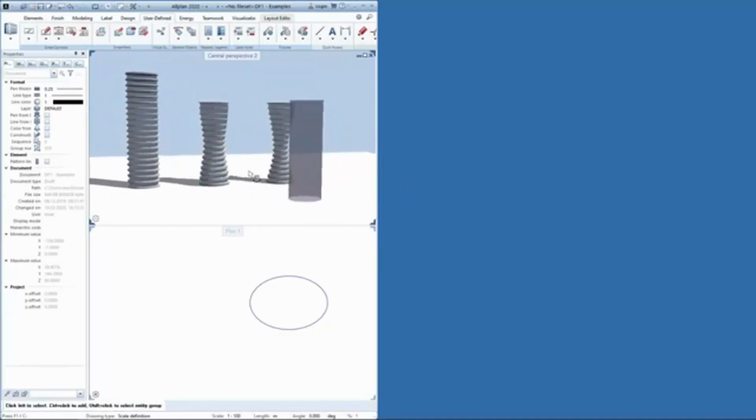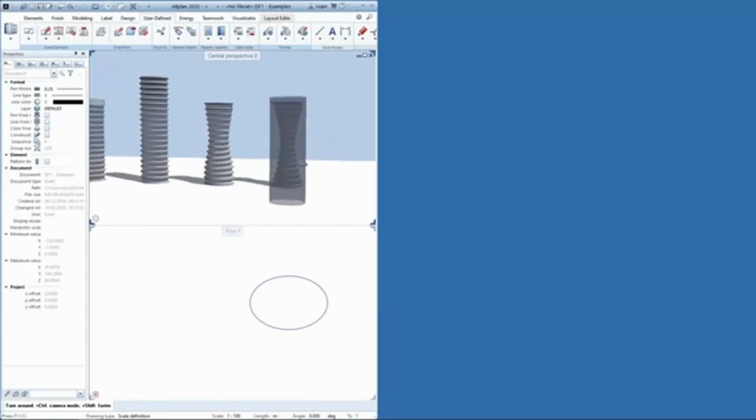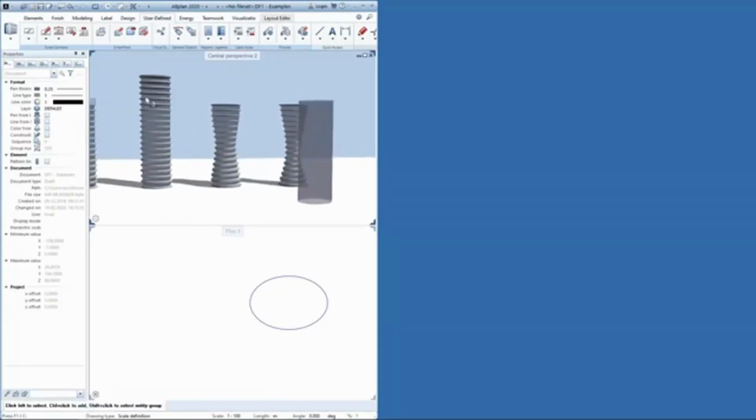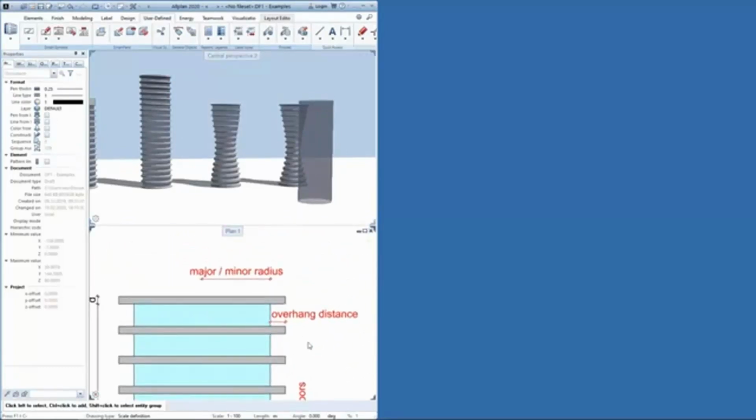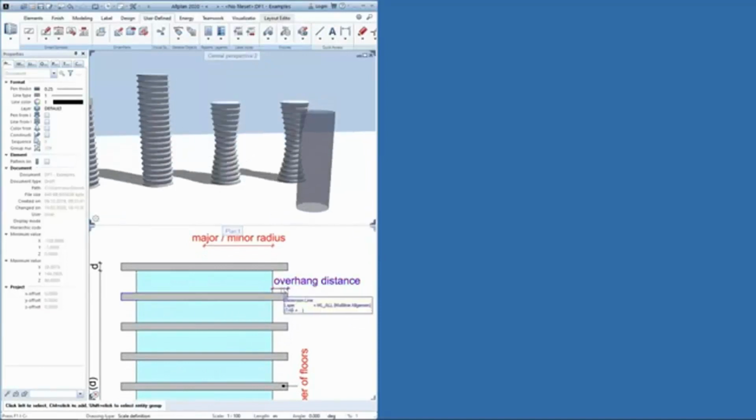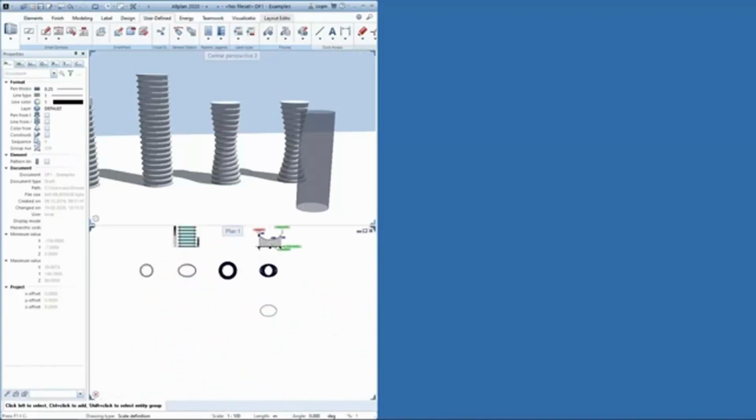So we have just created the first part of this first example. The second part is those slabs. So let's go back and see our sketch again. We see that the base form of all these slabs is actually an offset from the cross section of the glass facade. So that means if we can use some nodes to create an offset for us, we literally create the base form. So let's do it.